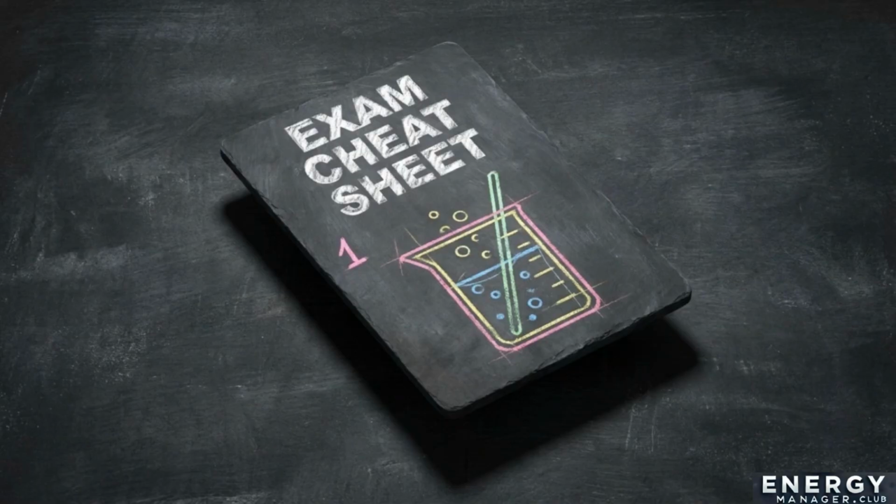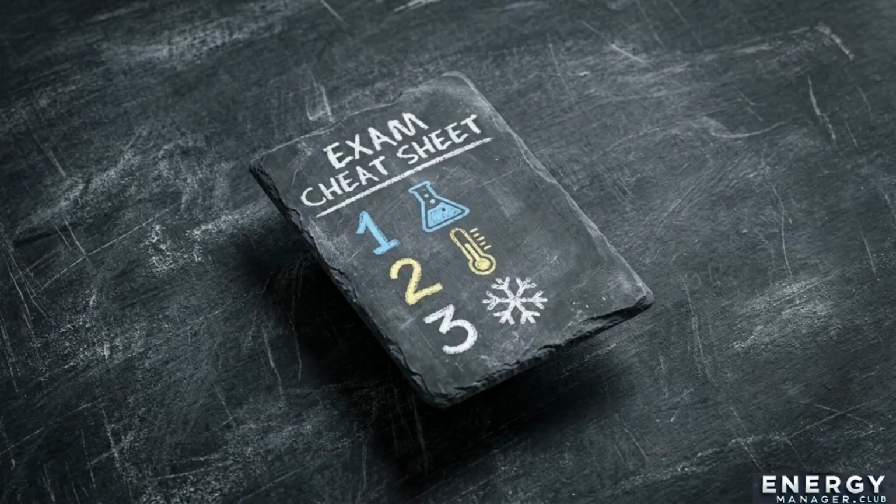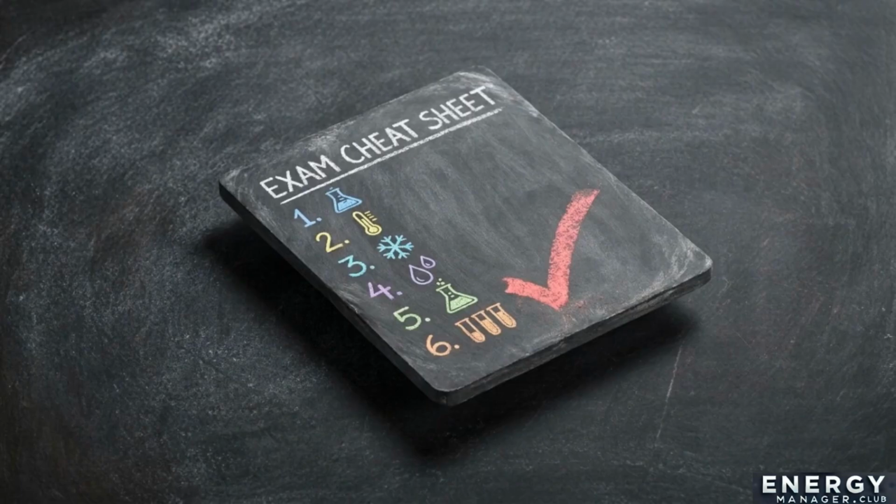When you sit down for the exam, use this exact 6-step chronological order. First, calculate the mixed inlet temperature. Second, deduce the range from the given TR. Third, solve for the cold water temperature. Fourth, find the approach. Fifth, calculate the effectiveness. And finally, compute the water losses.